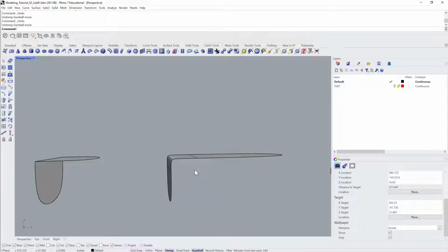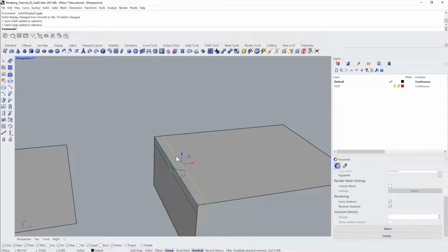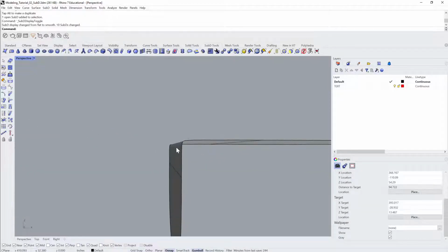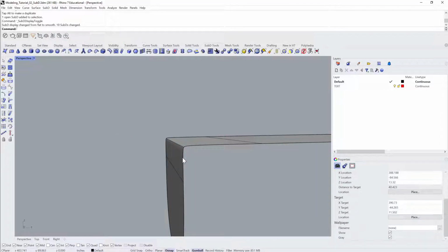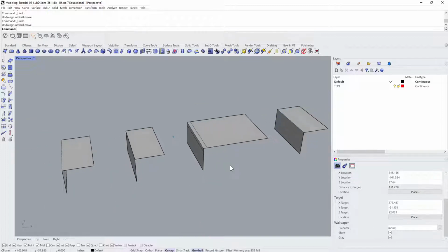And if I were then to go back to tab, move these edges really close to that edge, then we're getting closer to a crease then. So we get a little bit of rounding, but it's really, really now much tighter. So the closer, so we go back to tab, the closer these edges are to the edge, the tighter the turn is going to be.